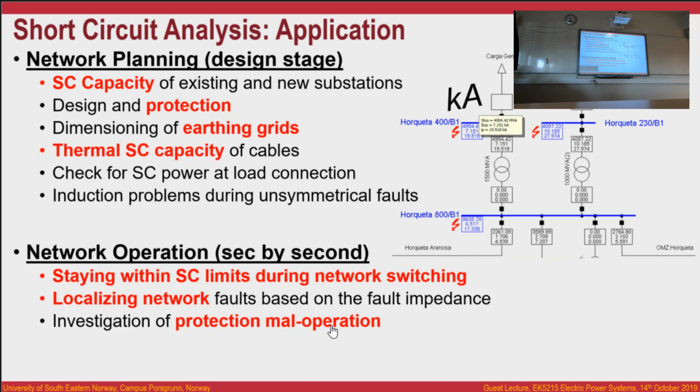For planning, I need the short circuit levels, because I don't want that transformer going on flames. I don't want a circuit breaker exploding. I don't want somebody dying, okay? But also, in the operation, second by second, I need those protections to be able to see if there is a fault or not.